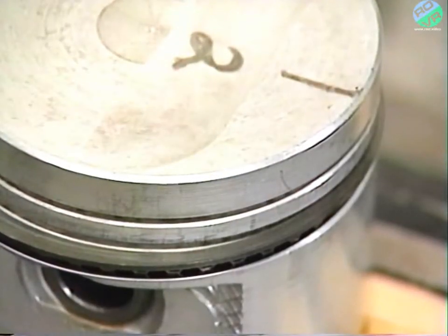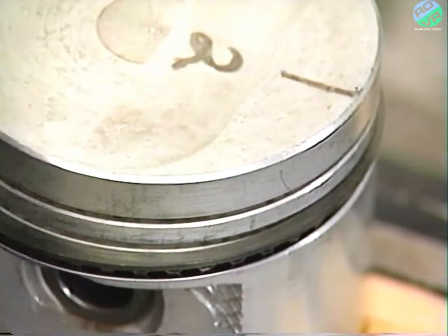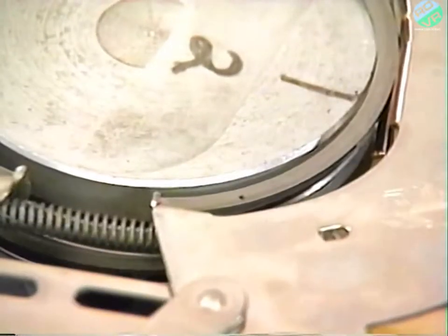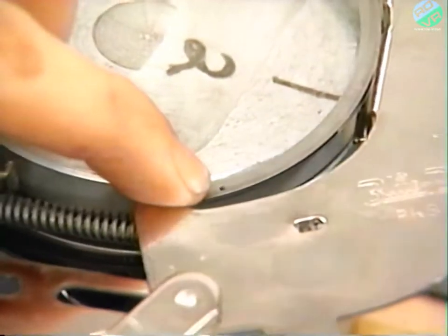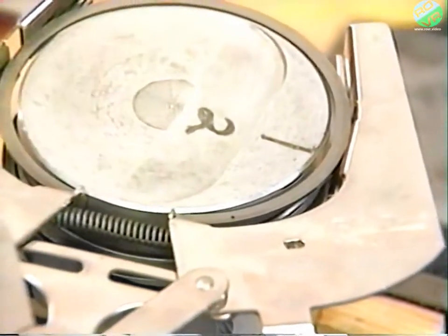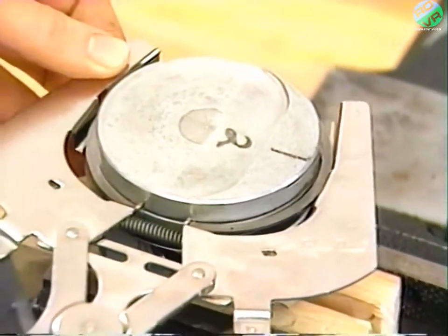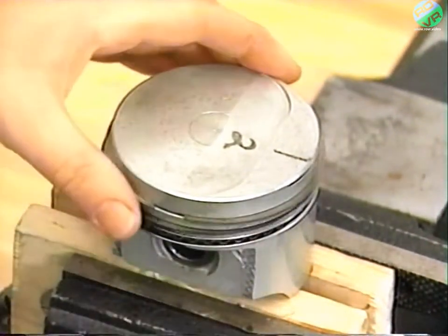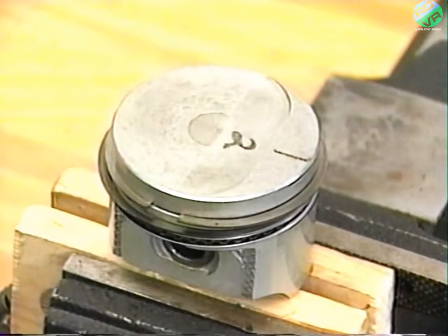Piston rings should always be installed using the correct ring expander tool. Install rings with the ID mark facing up towards the top of the piston. Be sure to check the service manual for the correct ring installation order, as this will vary with application.